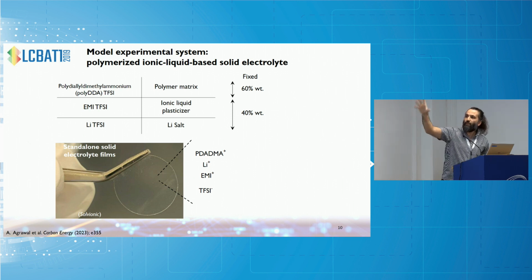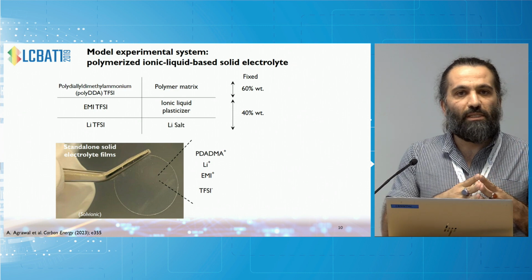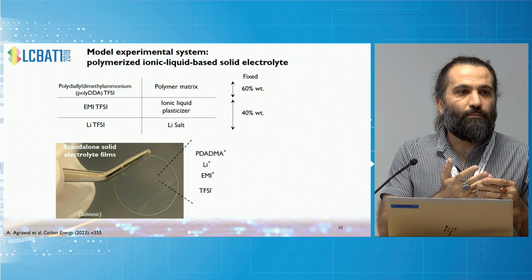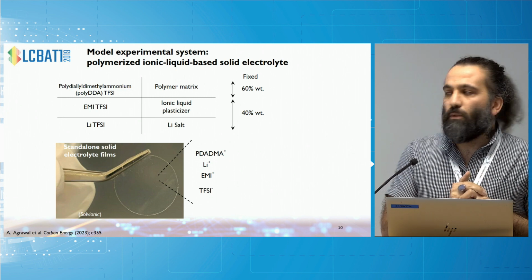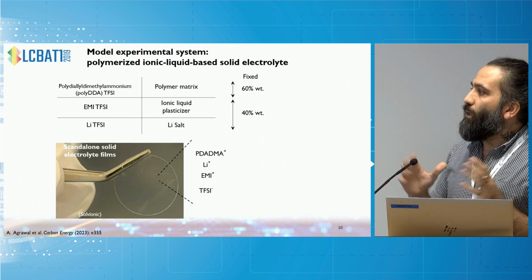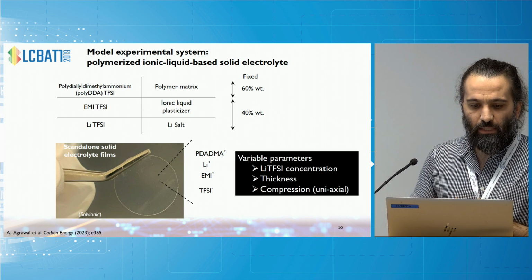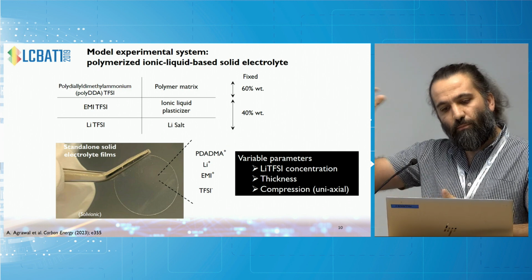This is the case study, and we were interested in how the transport properties of such a solid electrolyte are sensitive to the concentration of the lithium salt and the stack pressure. That was the idea. There are more parameters, but what I show here is mostly about the LiTFSI concentration and also the compression.